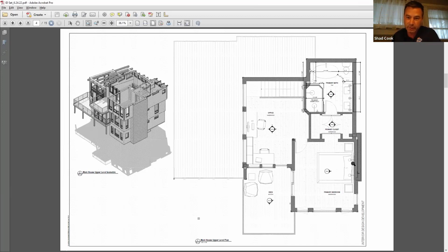So if we had two ducts there, we could potentially get a duct closer to that outside wall in the master bedroom, and then go along the top of that bookshelf with what would already be a soffitted area. Yeah, certainly the floor joists in this area are not going the right way for us running branches out here. Yeah, you won't be able to get out there, but you can get one in the corner there. You can perhaps get one here, possibly along the side of the bedroom there. Yeah, if the soffit on the first floor ran from at least here to here.